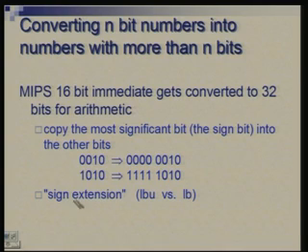Now minus 6 when represented as a 4 bit negative number gets us this. If the same minus 6 we had represented as an 8 bit negative number, we would have got all these positions filled with ones, okay. So in simple terms, we look upon this conversion as a sign extension. The sign bit is extended to fill up the additional bit spaces which you have. Okay.